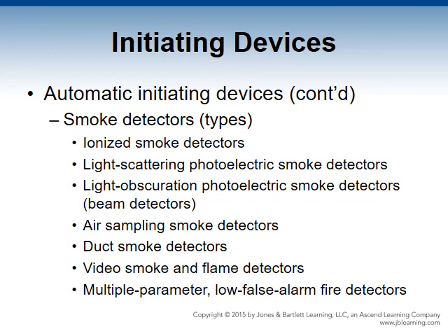This detector is common in locations where ceilings are very high, such as atriums or factories. The detector must mount on a stable wall or ceiling surface so that movement or vibration does not misalign the beam. Only well-placed beam detectors can replace multiple spot detectors.